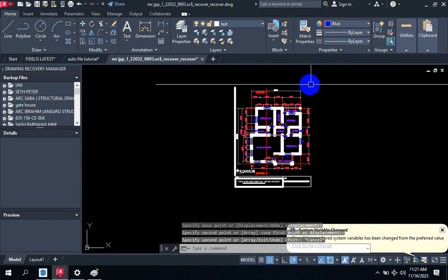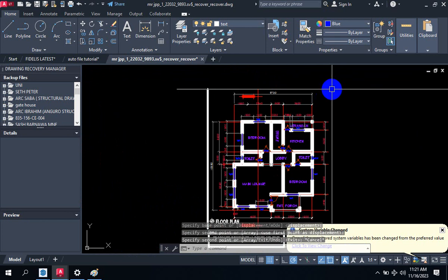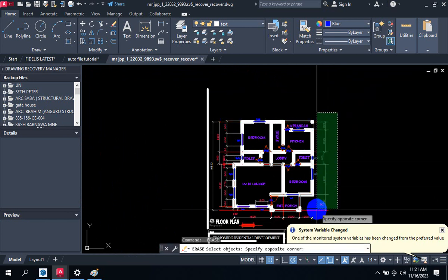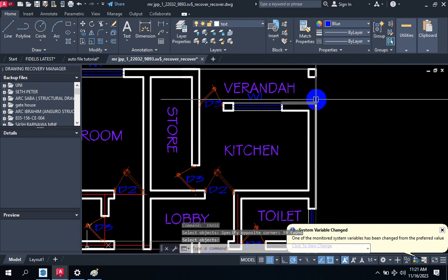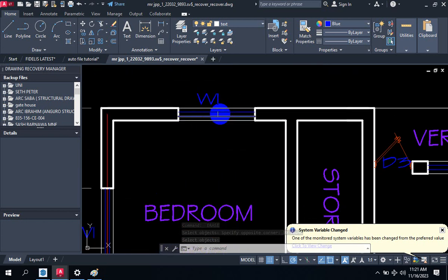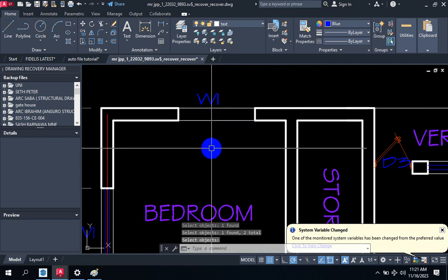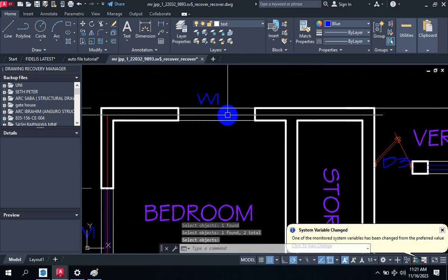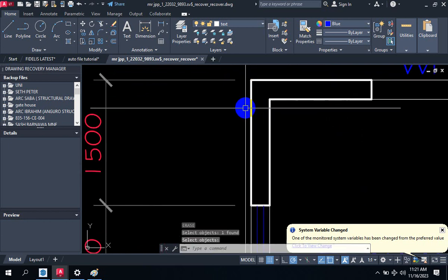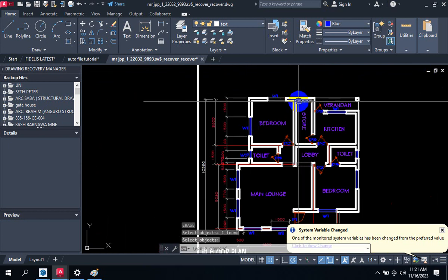So for example, if I'm to import one drawing, I need to clean up the dimensions, center lines. I can just leave the areas not opening, I can just leave them. One multiple lines thing is not going to be needed. I can just leave these two lines. So that's basically all I need to do, so that it will look very clean. It will be easier for me to extrude it.